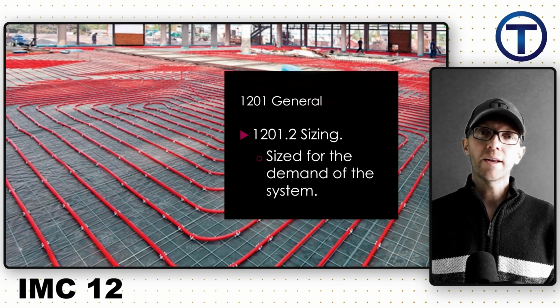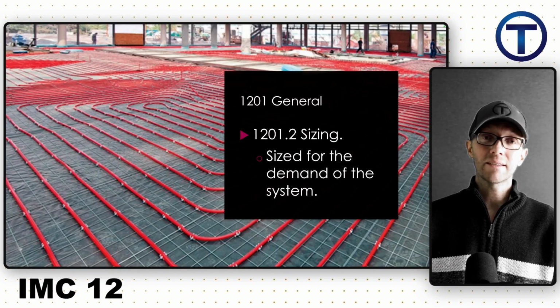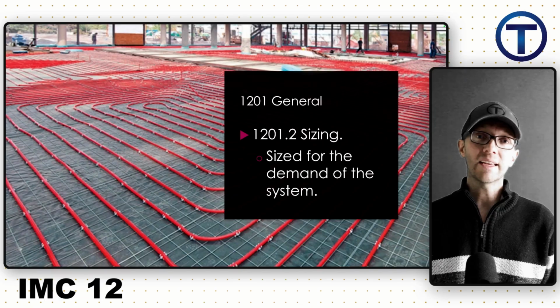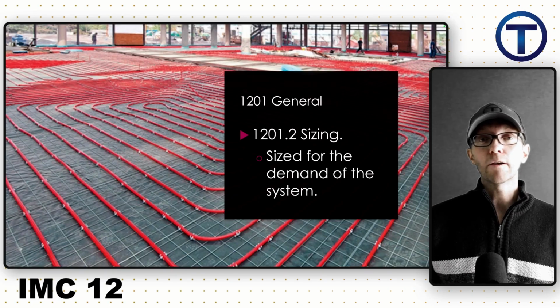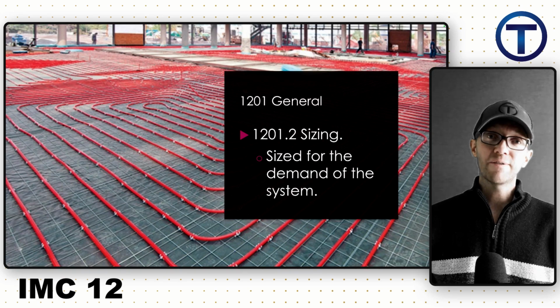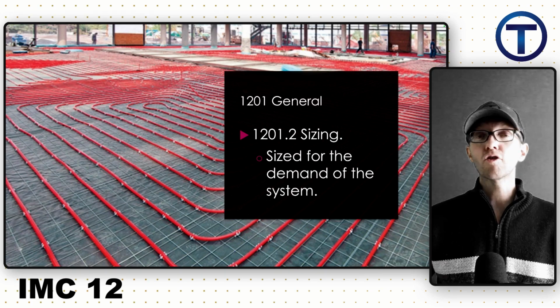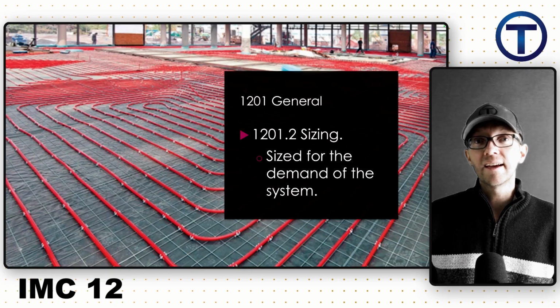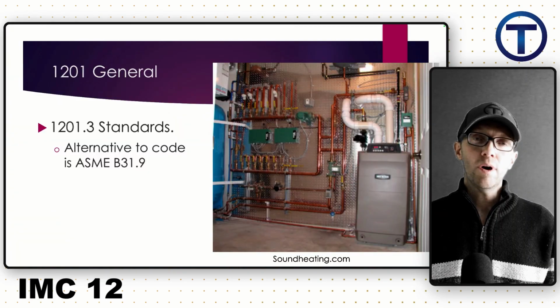Another issue that we find with a system that has not been sized correctly is that they're noisy because of the turbulence inside of that system. Now, especially as we're dealing with higher temperatures in a system, that erosion of the system happens faster at higher temperatures, and if it's not sized correctly, it's going to make it worse. Okay, so I've said a lot about that, but these need to be sized. You can't just shoot from the hip on this stuff.